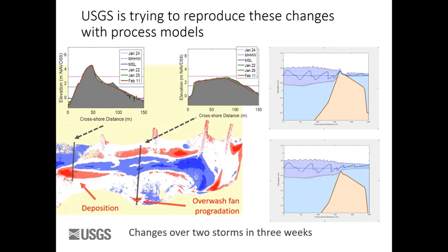Here's the little amount of sediment that deposited during that, and the integral of that sediment transport equation came out scarily close to the amount of material we measured here. So it's kind of an example of, and we're just starting to actually start using these maps now to make things like that, and to run models of what we expect the overwash to be. So here's overwash that's just barely overtopping, and the waves are coming over the backside and running down and then forming. Is this X Beach?